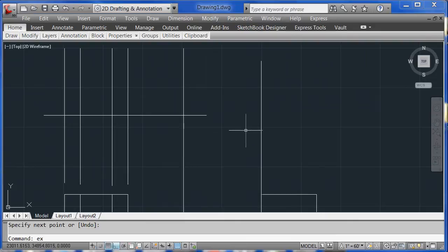Going ahead and using the extend command that you learned earlier, I hit EX, type the line that I want my second line to extend to, hit return, and then select this one, and then all of a sudden I have this point. Now, I want a 45-degree line coming out this way. So I type in line, and then again the shift right click for the end point, and AutoCAD rotates its angles counterclockwise. So I have to invoke a special command.